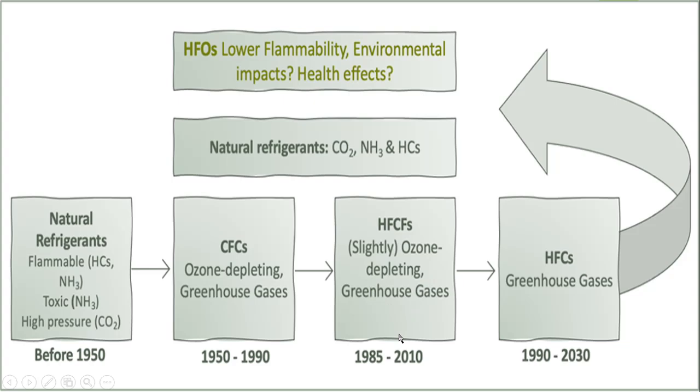So industry again shifted to hydrofluorocarbon, which has very little ozone depleting effect but still a greenhouse gas effect, and after that they came up with a new gas called hydrofluoroolefin, which has very low environmental impact, which we'll see in the coming slides. And now, because of 60 to 70 years of development in technology, the natural refrigerants which were neglected because of their challenges are back in the business because of evolved technology.